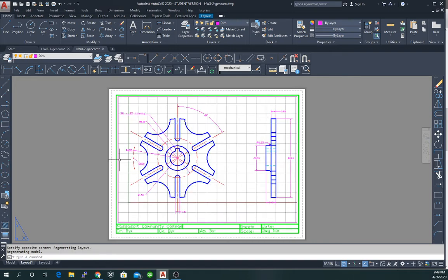And look at that, lo and behold, the drawing immediately pops out and it's there. Well, a lot of that has to do with the fact that we put it in the right location. However, it is possible in a viewport to move what you're seeing around so that you can actually choose different portions of the model space to view in your drawing. So for instance, we could set this up so that we're only looking at one drawing. We're only looking at, let's say, the left-hand side, or maybe we're only looking at the right-hand side. Anyway, what do we want to do next?